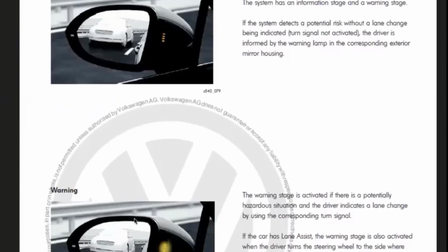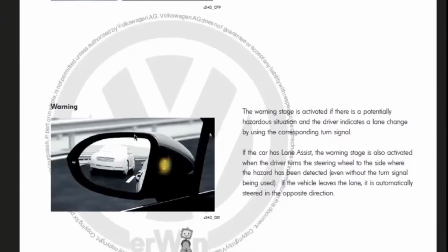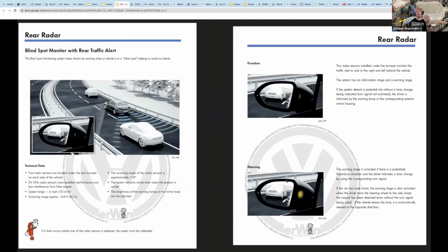So the big thing I've learned about ADAS systems is it's kind of like, when you go to the doctor, a lot of doctors are very compartmentalizing about the human body, but in reality, the human body is one cohesive unit. And if something is broken over here, it can affect things over here. So in this particular case, we have a light burned out, essentially, is what the fault code says, or a short in that circuit, or something of that nature. So the health of the system is not intact, right? The warning light is part of the total system health, and the warning light is not functioning on the left front mirror. So that tells us we need to fix that fault before the system will calibrate and work normally.